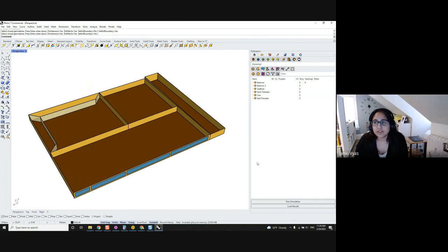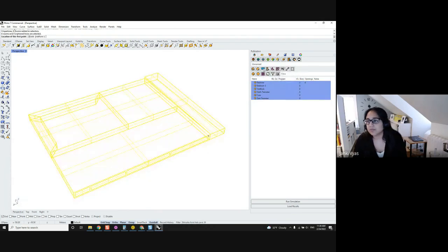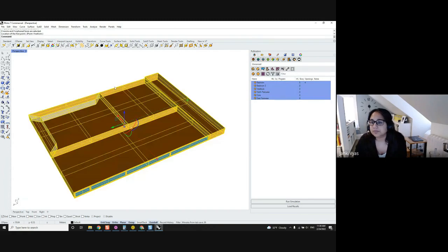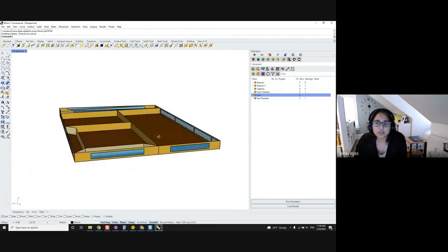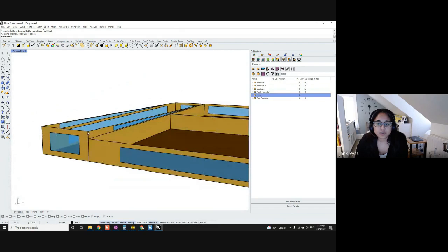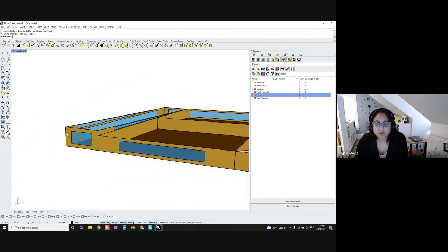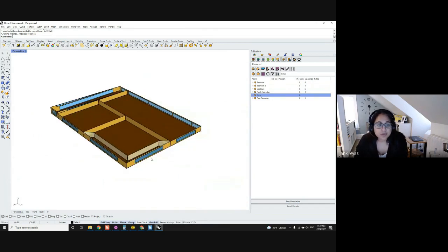So we are now ready to apply window by wall ratio. I can select all of the rooms and say draw add window, add by window to wall ratio. I'll keep everything the same and let that run. It will run faster this time because it's not trying to add windows to all the interior surfaces. And you'll notice that even that slightly sloped roof that we have gets windows added to it based on the window to wall ratio script. So that's adding all of it.